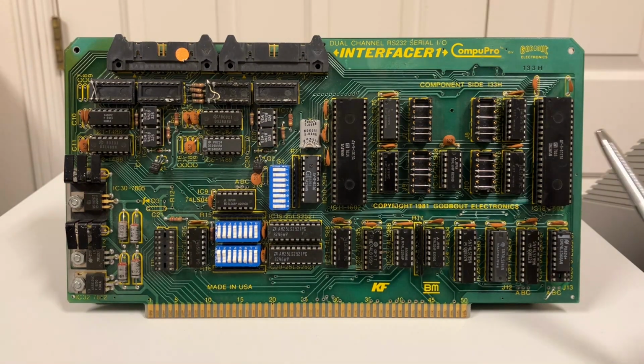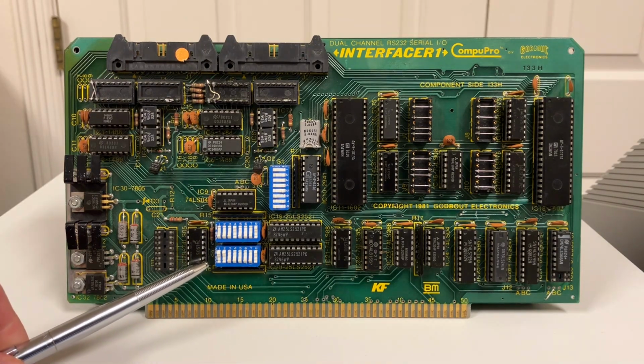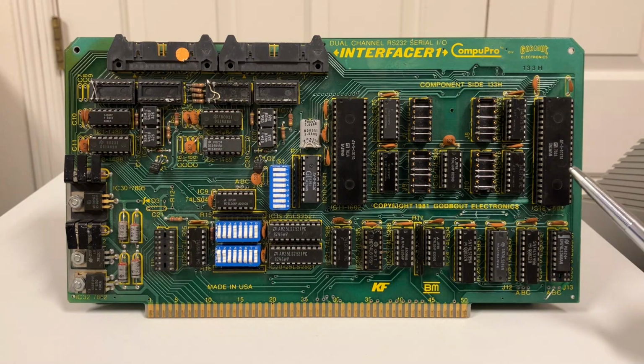But going on, we're going to first just look at how do we make this work as the cassette like we have for the other boards. First thing we need is IO addresses at 6 and 7. That's done on this lower set of dip switches, which sets the starting address for UART B at 6. And then, of course, the next register to be 7.